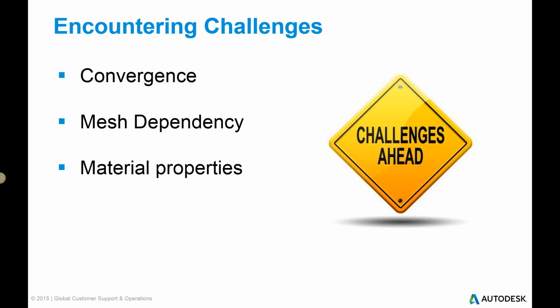And then lastly, we get a lot of questions on where to calculate or how to calculate these material properties and where they come from. I'd like to just note that determining these values involves an iterative process focused on calculating the cohesive stiffness properties and calibrating the initiation strengths.